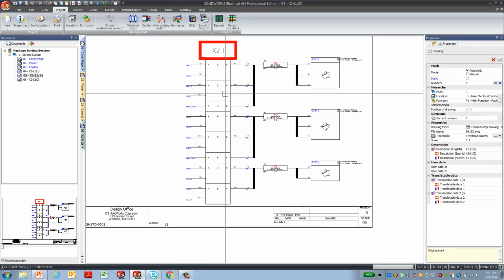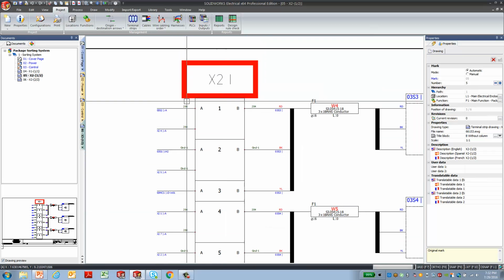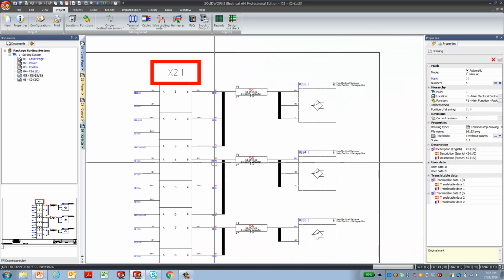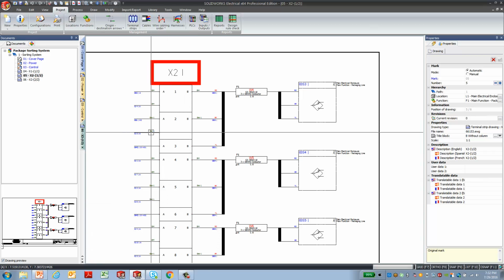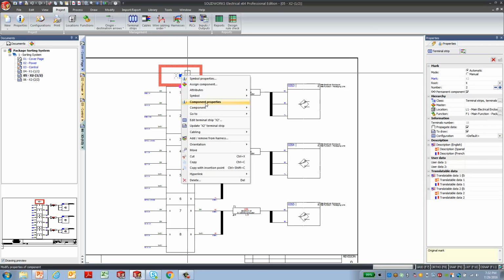Okay, so something we notice here, we have a lot of wire 204s coming into this device. That's because everywhere we have a power terminal, we're jumping out to get down to the next one. Every 3rd input is coming off the power. Every 3rd input is coming off the ground as well. So what I'll do is I'll just add some bridges in here to make this design a little neater here.